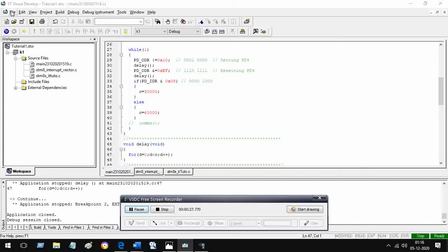Then there is an interrupt due to timers, an interrupt from the AD converter, an interrupt from the clock, and an interrupt from serial data coming in. Likewise, there can be a variety of sources of interrupt. And out of that, we are going to use interrupt due to input ports where we have connected 7 different keys, and interrupt due to serial communication because the MP3 module keeps talking to the microcontroller on the serial port that we have seen before.